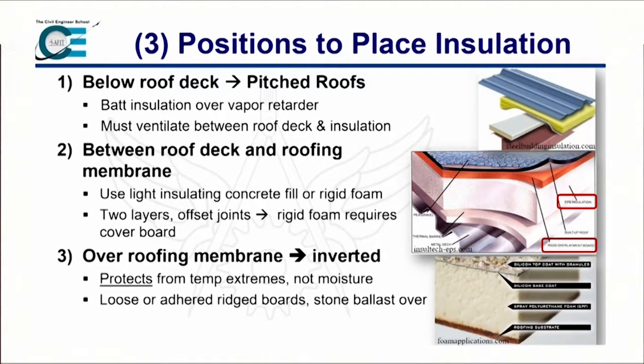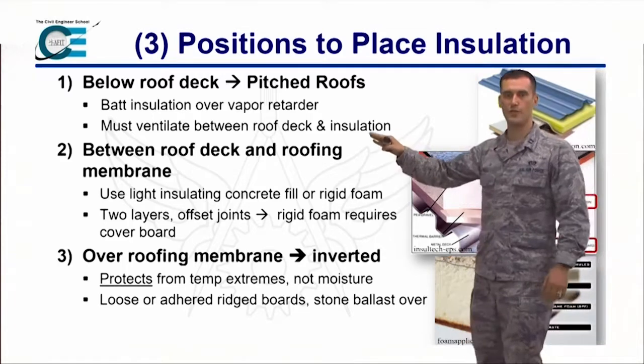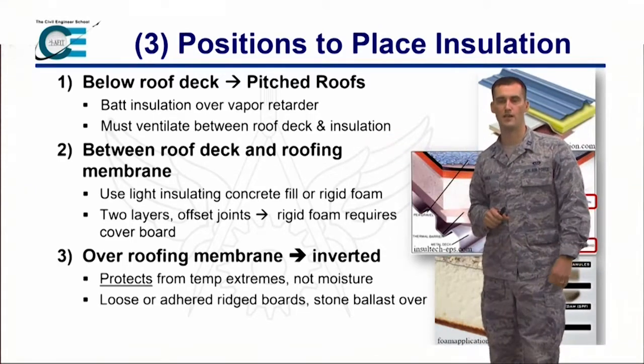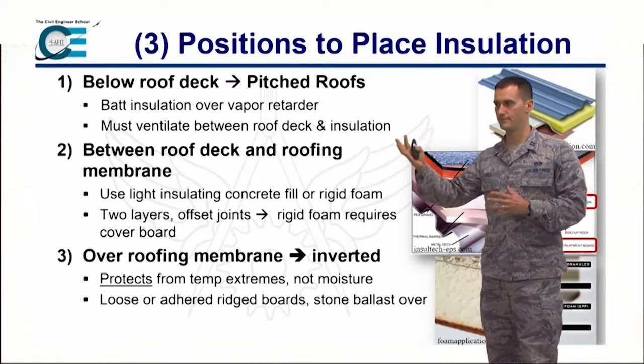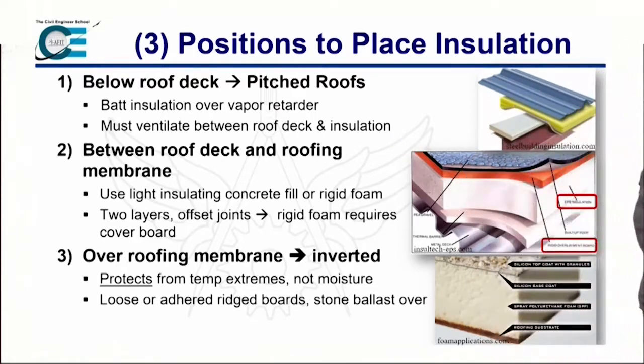Or even, I suppose, it's below the roof deck in a typical configuration where it's just laid on the top. So in this case, you're going to want to ventilate that space between the roof deck and the insulation. So the attic at my home, I'm going to want to ventilate this because a lot of heat is going to be stored in there, and that can cause issues of condensation, which we'll take a look at.